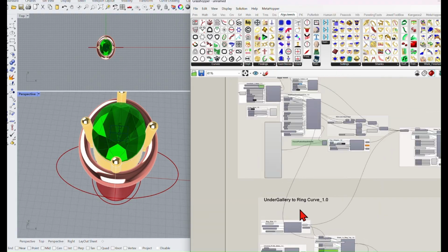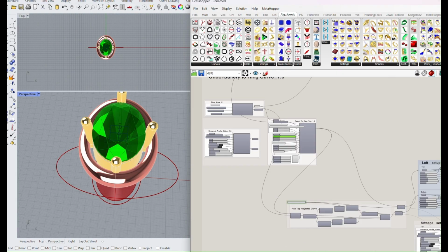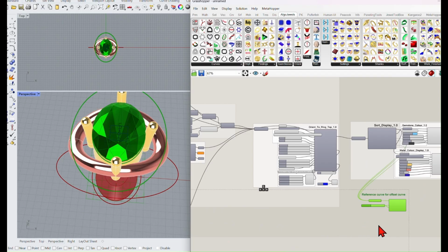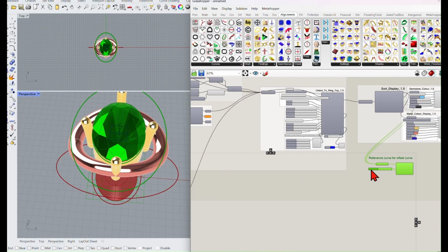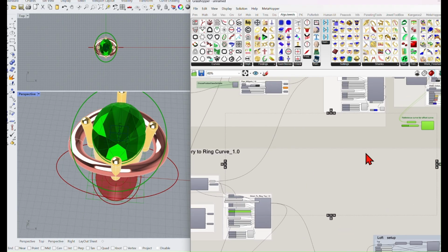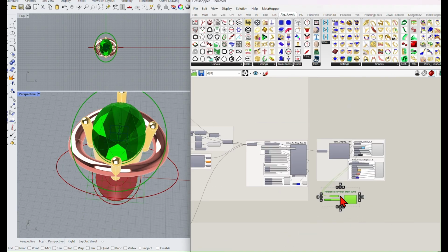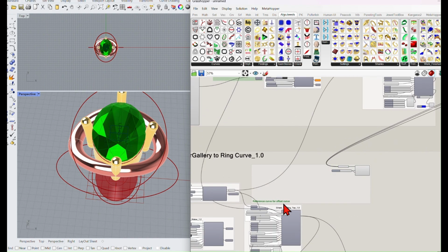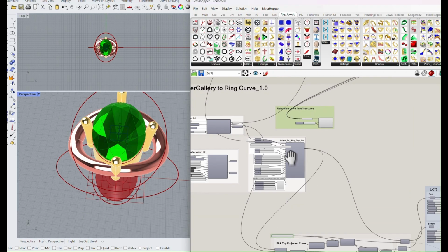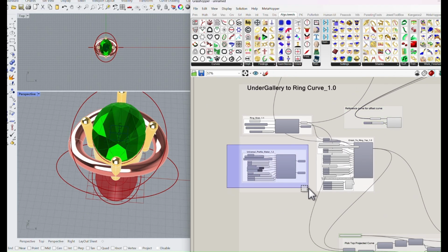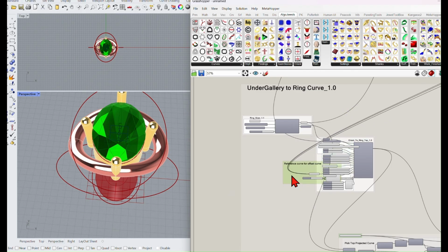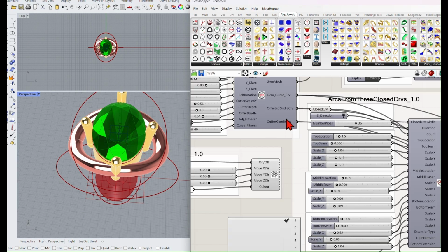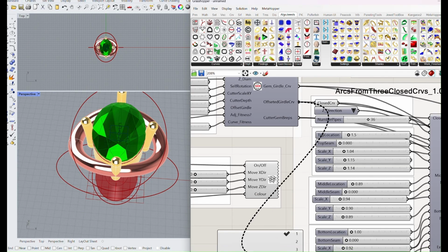And we can actually, here's what we need to do. Let's go Control Z, Control Z, Control Z, Control Z, because we need this scalable. Scalable. So let's go like this, group this, bring this group down to here. We're not using the universal profile maker. We delete that. We're going to use the gemstone curve, and we're going to bring in the offset girdle curve.